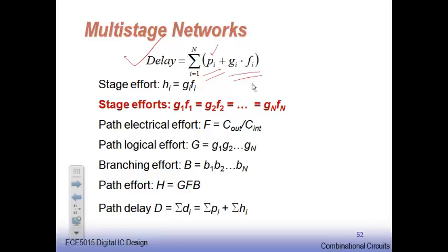And for that, what is the logical effort? How much is the fan-out load? And in this, the stage effort, how much is that? Gi times Fi. Fi means what? I am driving the Fi plus 1 and this is driven by the Fi minus 1 stage.